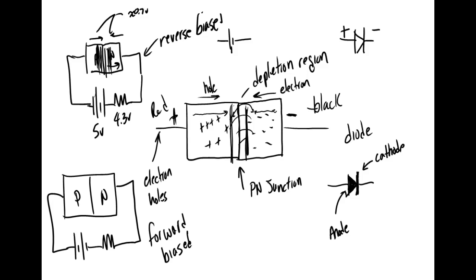Now it's not pretty DC, and we'll look at that before long. We call it pulsating DC, but it is DC. A DC motor would run off of it fine. They don't care. DC motors look at it as an average. They don't care if it's pulsing or not, as long as it's pulsing at a rate that it can average it out, right? You understand?